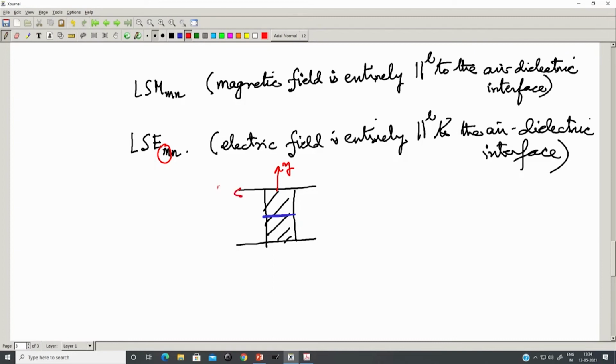So, this was my x. So, this describes the transverse variation of the fields along the x direction inside the strip. This can be either of the cosinusoidal or the sinusoidal type. So, inside this strip the variation can be even, or cosinusoidal type, or odd, which is the sinusoidal type.